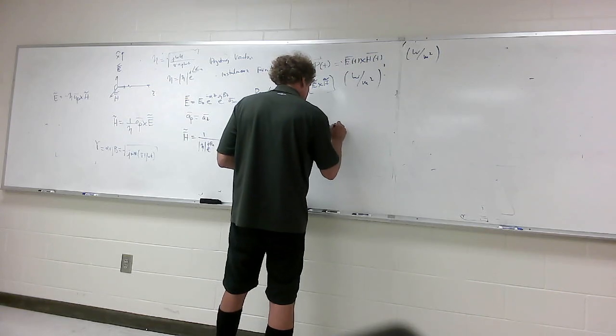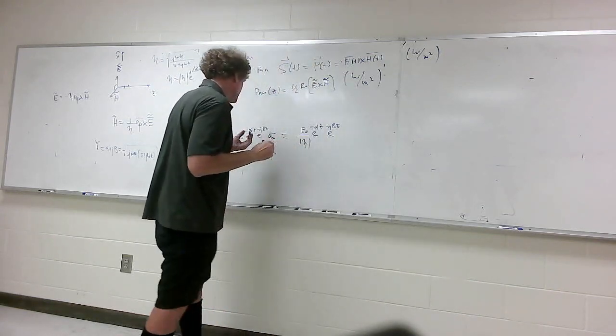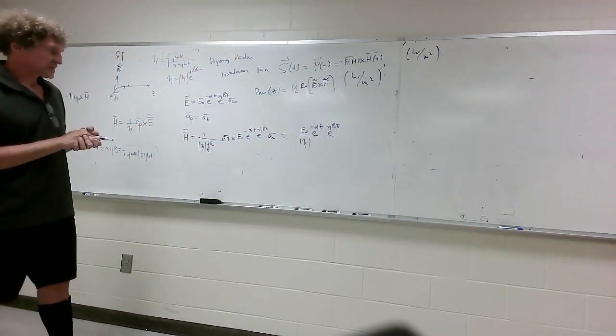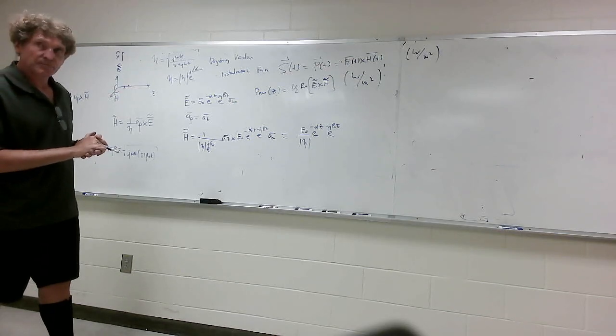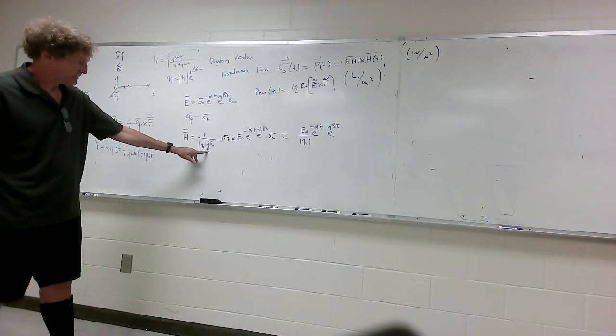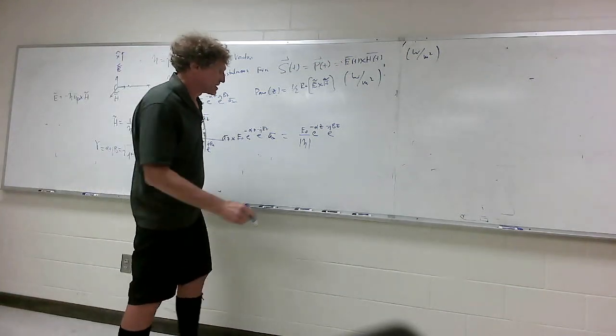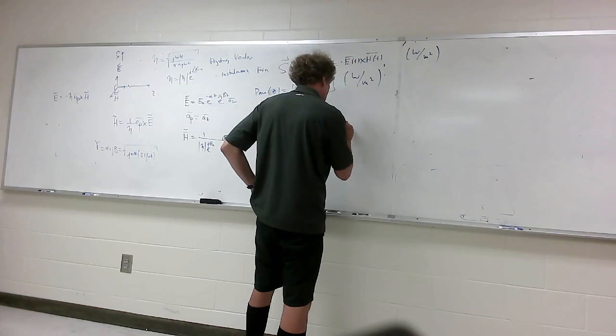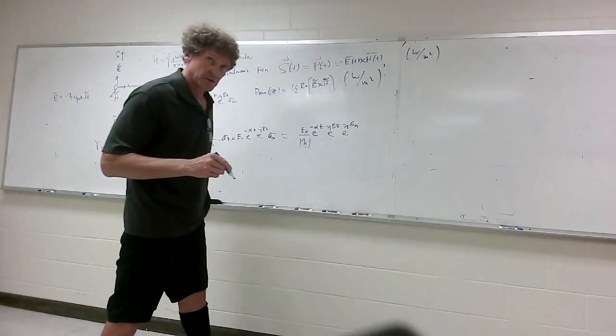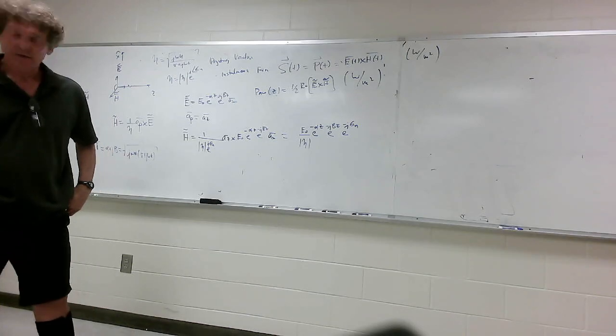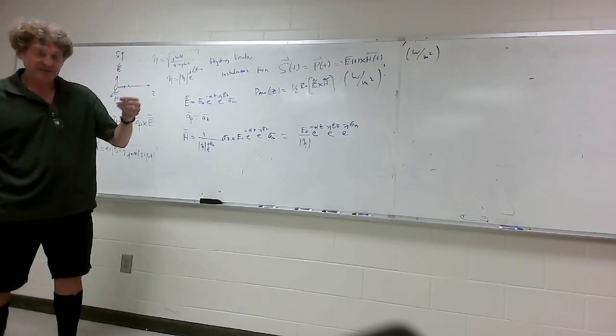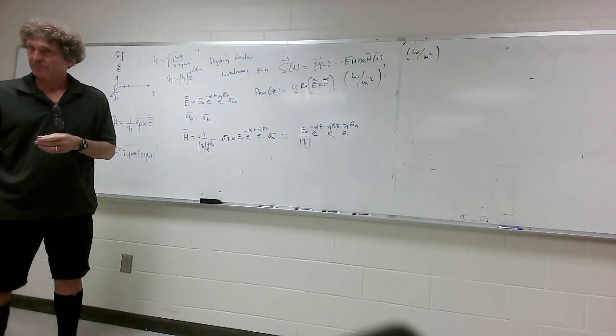So I'm just repeating all the terms that have no real vector sense to them, or angle. Now when I take a look at this one, I have 1 over e to the j theta of eta. When I take it upstairs, it becomes e to the minus j theta associated with the intrinsic impedance. Because if it's plus downstairs, it becomes minus upstairs. Everybody okay with that?